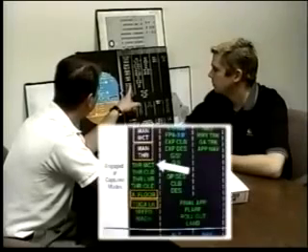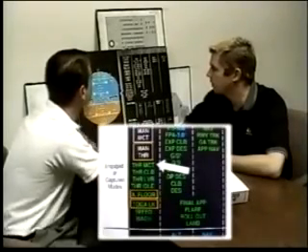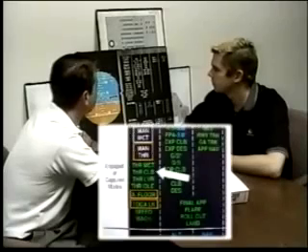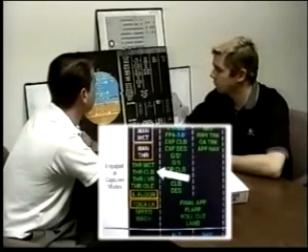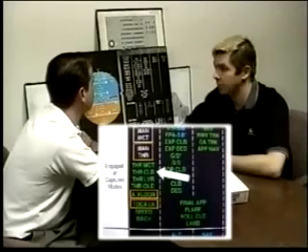Let's move down to the engagement modes. Thrust MCT. Thrust MCT means that the operative thrust lever is in the MCT detent, and the auto thrust is engaged. And it's commanding? It's commanding MCT thrust only. What about Thrust Climb? Thrust Climb means that the most forward thrust lever is in the climb detent, and the auto thrust is engaged. You get climb thrust only.